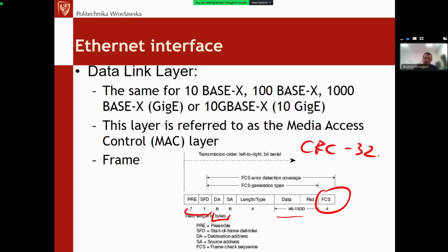And that's another important fact about the Ethernet interface. When we have a microcontroller implementation of Ethernet, we need to be able to generate this CRC, which means that the core itself, or the whole microcontroller, needs to be able to calculate the CRC in a short time, out of at least 60-some bytes, and maybe out of 1,000 bytes or so.